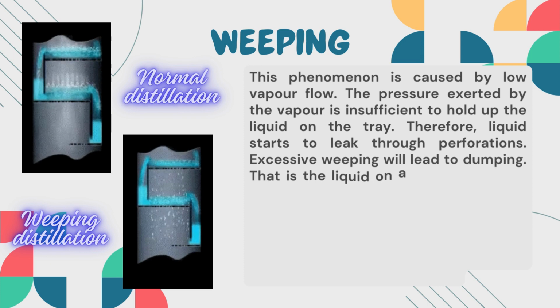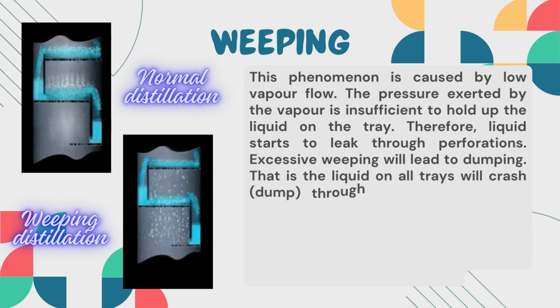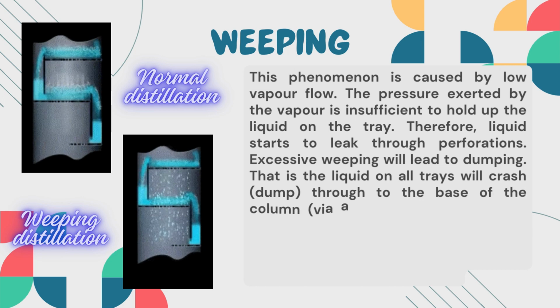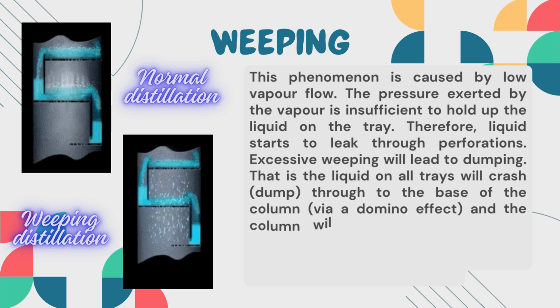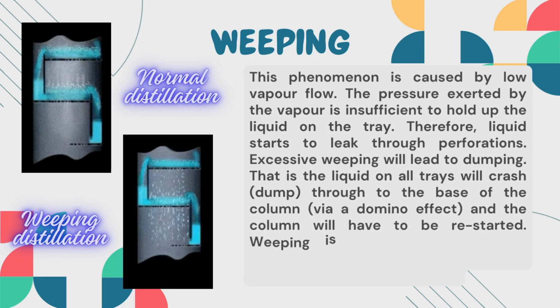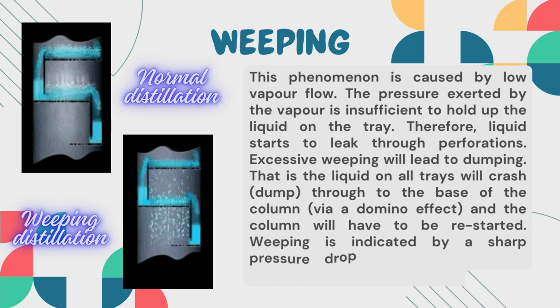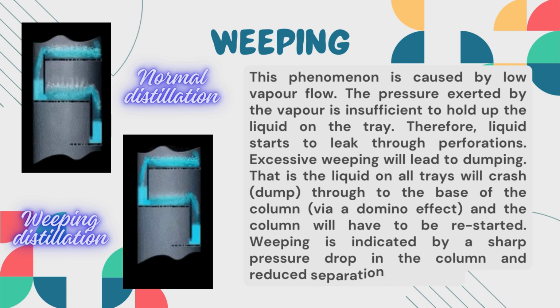Guys, excessive weeping will lead to dumping, that is, the liquid on the trays will crash, that is, will dump through the base of the column, and the column will have to restart. Okay guys, weeping is indicated by a sharp pressure drop in the column and it reduces the separation efficiency.